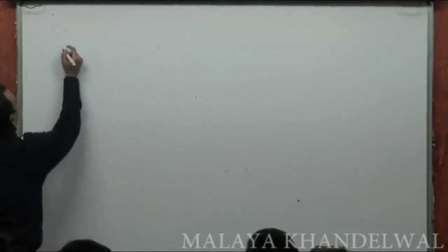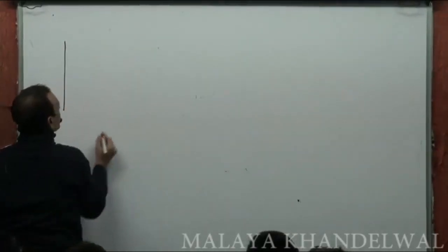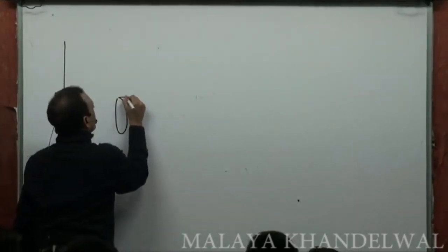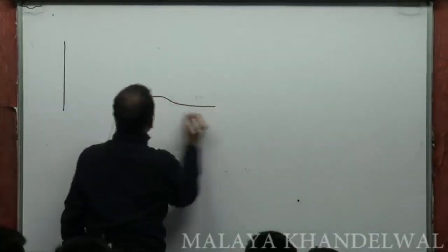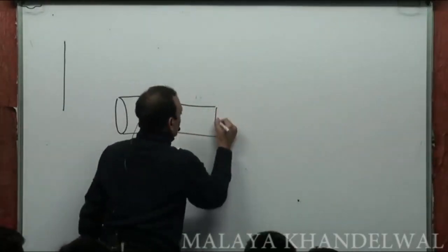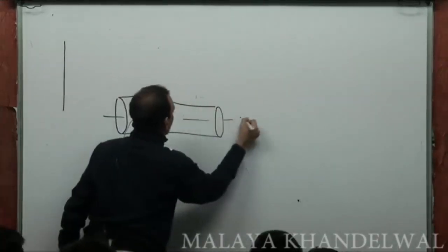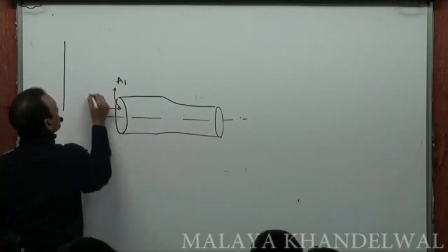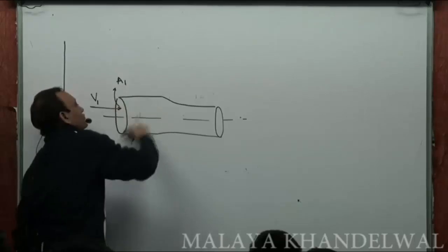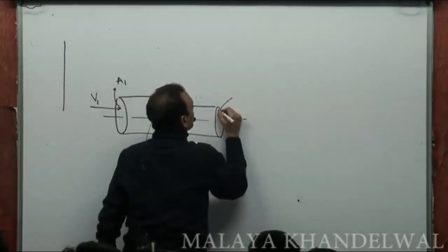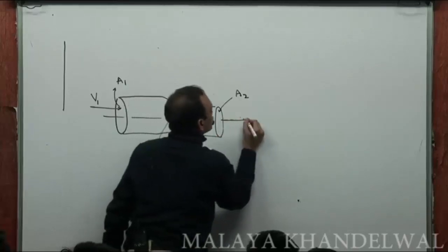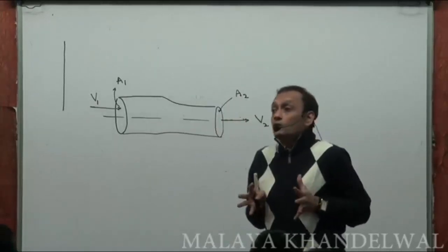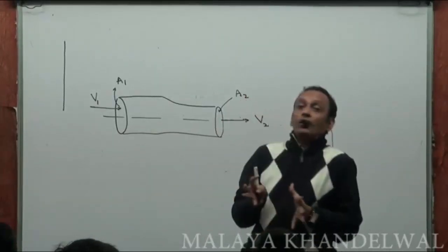another fact that I want to make a very explicit mention of is the equation of continuity, which is like, if there is a flow occurring in a small channel where the datum is not varying significantly, and if this area is A1 and the velocity of the fluid entering this area of cross section is V1, and when it leaves with an area A2, then equation of continuity means that there is no deposition or accumulation of fluid anywhere.